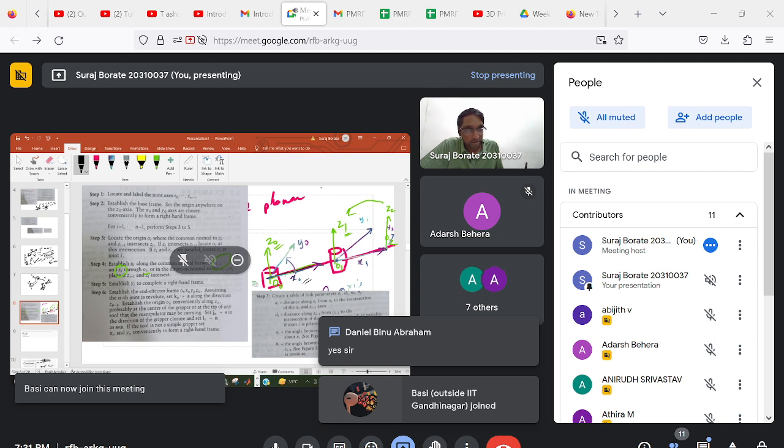Okay, so this is distance along xi, right, a1 a2, and so a is always in the direction of x. Along the direction of d you have 0 distance, so our d1 and d2 are 0. So what are a1 and a2? These will be the link lengths l1 and l2.